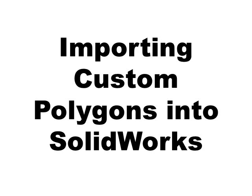It has one thing that kind of looks like that. A little spreadsheet pops up and lets you enter a whole bunch of different vertices, but it turns out it fits a spline to it, which is a smooth type of line. But if we really want those vertices fixed, at least up to the 2010 version of SolidWorks, we weren't able to do that. And I am a little bit out of date, and I probably need to check on that again.